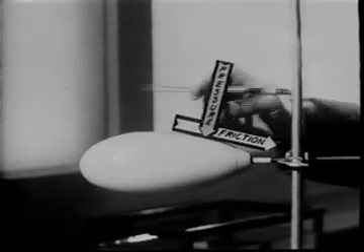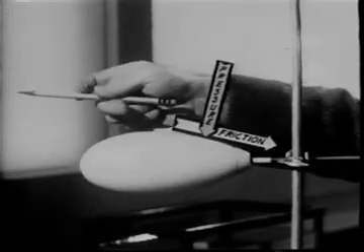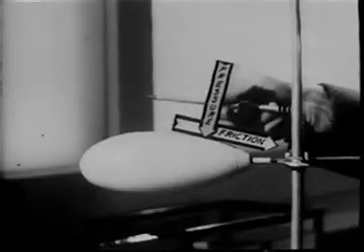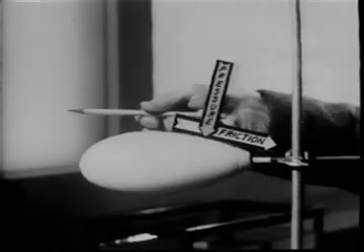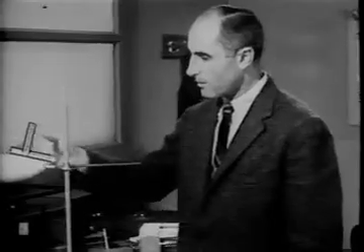Adding up all such components for all elements of the body's surface, we get two contributions to the total drag: pressure drag and friction drag. Friction drag is always present because all fluids have some viscosity. But the pressure drag may be either very large or it might be quite negligible.